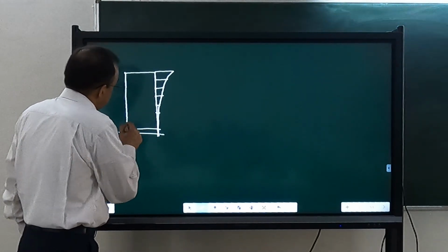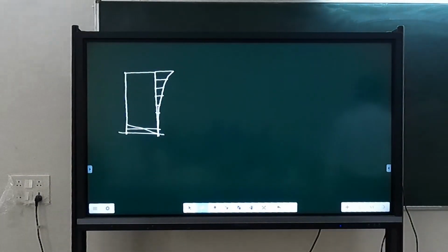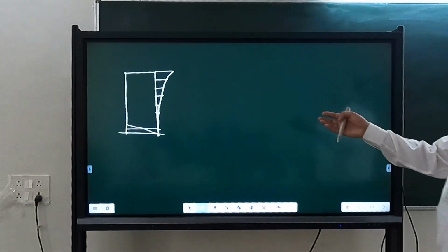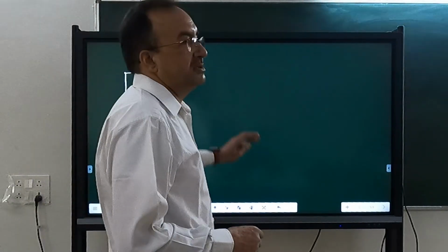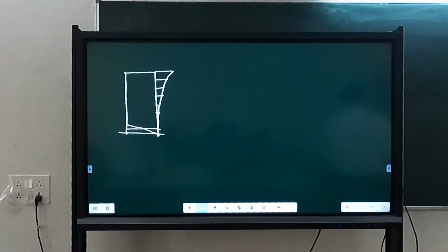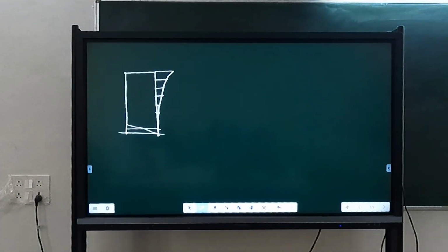When it yields here, it will rotate like a rigid body. And the additional displacement is simply the plastic rotation into height. The second component in that delta corresponds to this part. So up to yield point, it is like a cantilever. We have obtained the deflected shape from the curvature diagram, and after yielding occurs, it will rotate like a rigid body. So that also I have given.